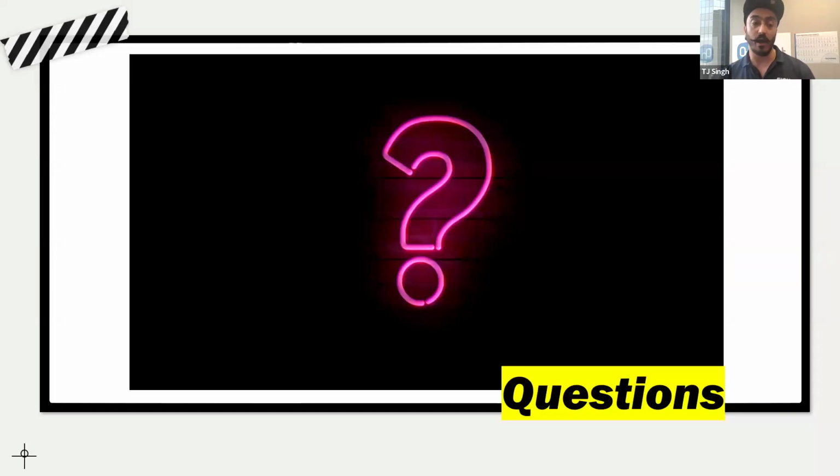Okay, we got one that came in here just now. Someone asked, can you change the configuration on the Flexi Compact over Ethernet? Yes, so you can do that. That's why we have that port for the Modbus TCP, so you can use that and also connect it over serial, how I have it right now, but those are available options.